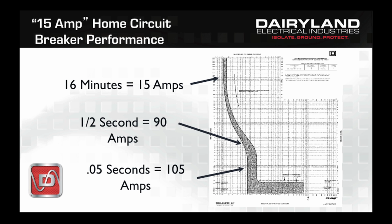So let's say we had a direct short in our house, a light bulb or a motor burnout, or something happened to cause a direct short on the power line. You can see from this chart that for a very brief amount of time, such as say 0.05 seconds, the circuit breaker will actually pass 105 amps before it were to open.